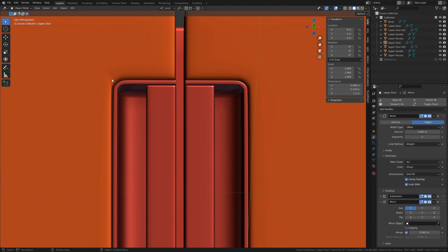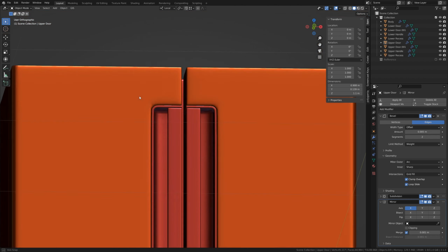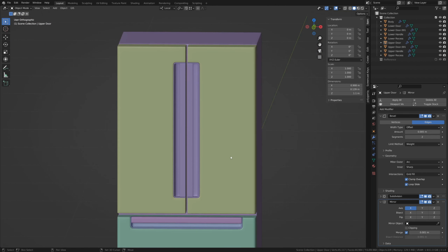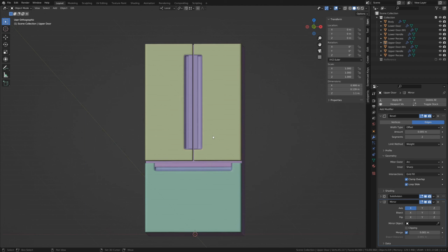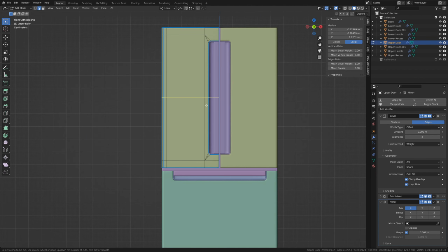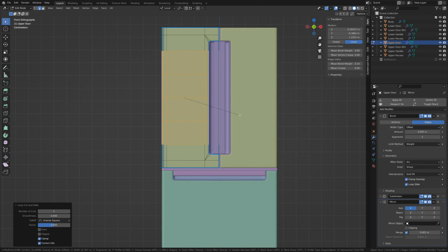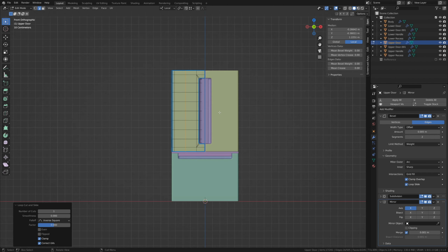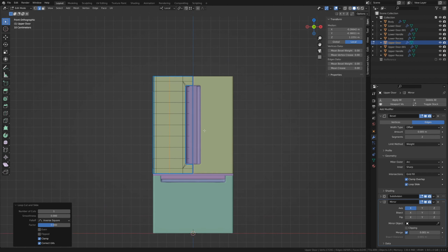It looks like we have a little bit too much of a stretch here for the smoothing to happen with our subdivision surface modifier. So let's go back to our studio view and deal with some of the subdivision of our mesh. In front view, let's add one cut along the center, and we're going to bevel that up a little more. There we go. We want roughly squares as much as possible around the mesh. It helps the subdivision surface modifier to work a little better.